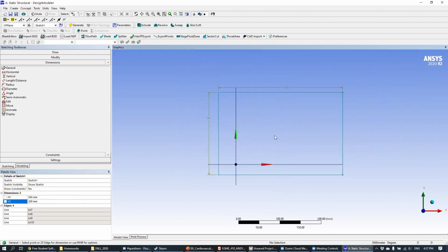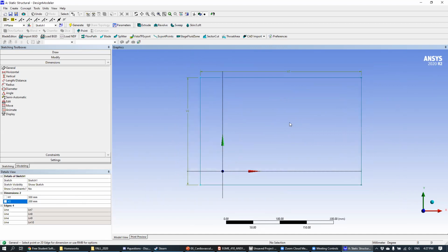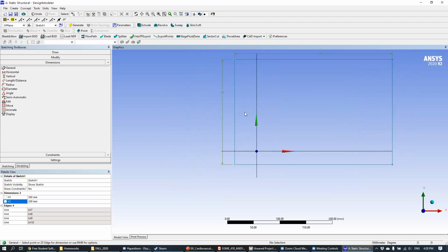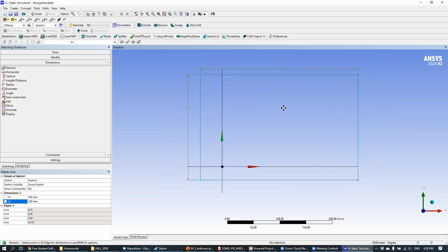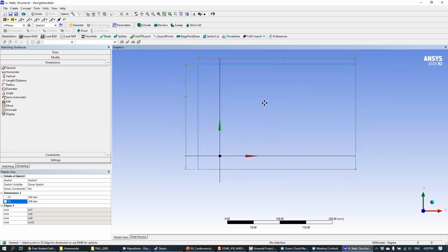That is done right there, okay? And so if you're kind of like me and you had to enlarge the screen, you can scroll on your mouse wheel to zoom in and out, and then to pan within this plane, I hold down Control on my keyboard and I hold down the middle mouse click, and that pans the view, okay?